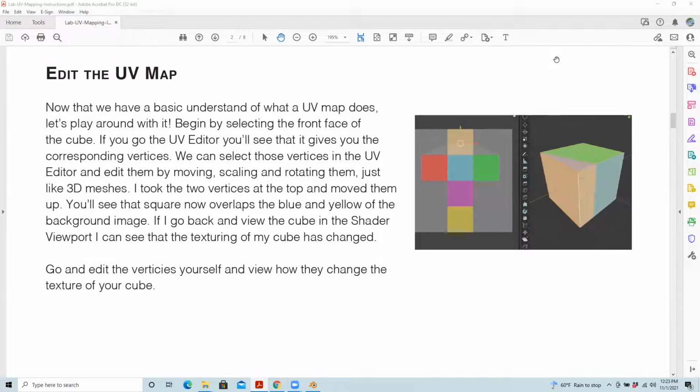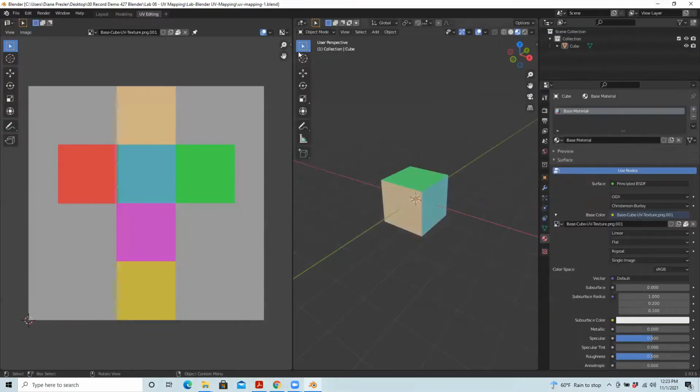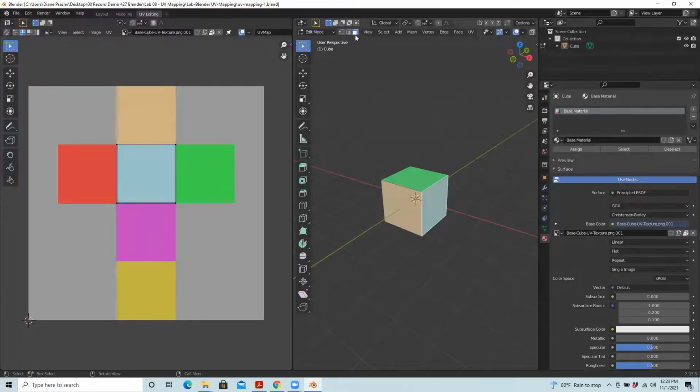We're going to try a little interesting experiment to see that you're able to actually edit the map, the shape, and then that would reapply the texture in different ways, which is one process of working. So we'll go back into Blender, and I'm going to switch back to edit mode instead of object mode and make sure I'm in face select. And you can go ahead and click on one of the faces. I'm going to click on this side face and remind you that it's highlighting the edges of it over in the UV editor tab.